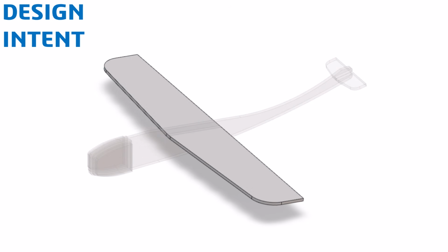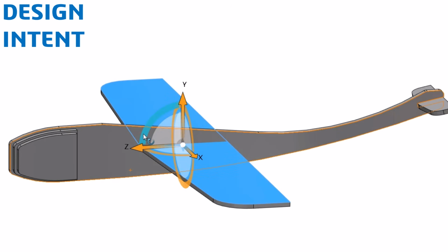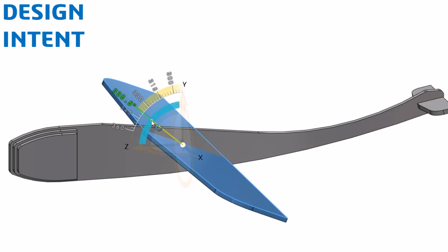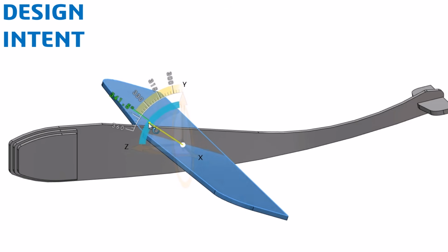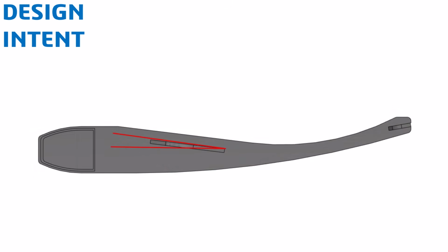The angle of the wing is also very important, and is controlled by its cutout in the fuselage. If we tilt the wing too far back, the plane can stall, but if we don't tilt it enough, it won't generate any lift and will fall to the ground. A wing angle of around 5 to 10 degrees is recommended, but depends on your specific material choice and desired flying style as well.